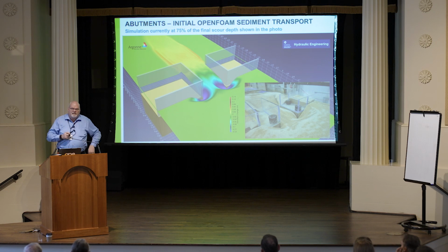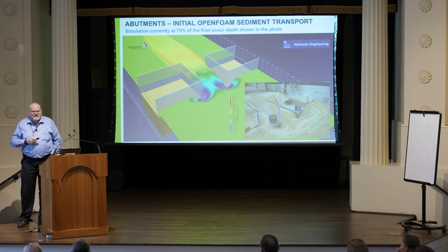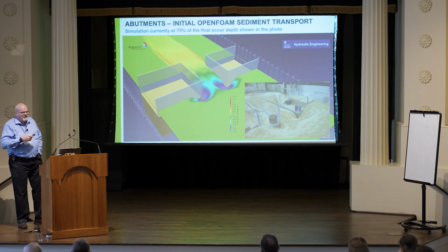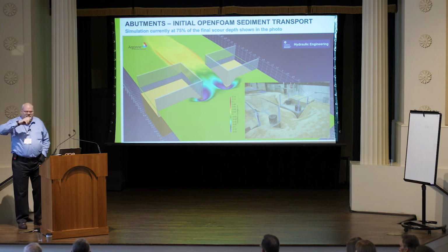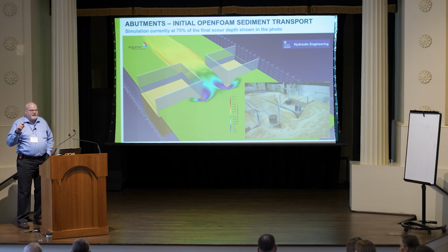The most material you can pack in the first layer is 60% anyway. That's the packing density of sand and water at this 1 millimeter diameter. So we are transporting a layer of sand, but it's probably quite a few grains thick. And so at that point, how do you properly describe friction and things like that?